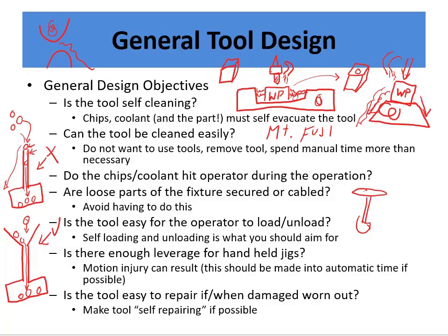And sometimes you'll see tools that are very difficult to load. The setup time is usually what takes so much time, so you want to avoid your setup time. You want to make tools that are easy to load or fixtures that are easy to load. That's what you should aim for. Ideally the marbles come in a big box, and then we just cut the box open, and they all roll down a chute, and then they fall down into here. We don't want to have to pay a skilled worker to wear cut-proof gloves and pick one marble at a time and carefully hold them over to this tube and risk cutting their fingers or dropping their marbles and losing their marbles. I want to make it as easy as possible.